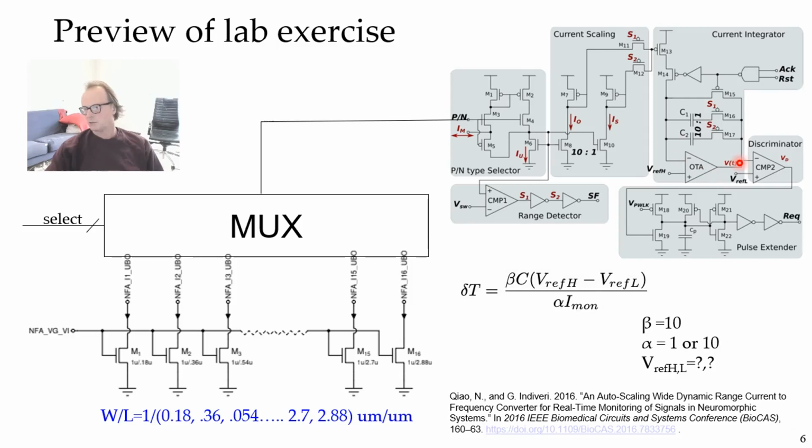And then this feedback loop charges up this circuit until it crosses the threshold, Vref low and high. So it keeps doing this like a neuron, right? It's like an integrate-and-fire circuit. It keeps going around, going up and down like this. And then what results is a stream of pulses that go off chip, and these are connected to the counter unit on the Teensy microcontroller.